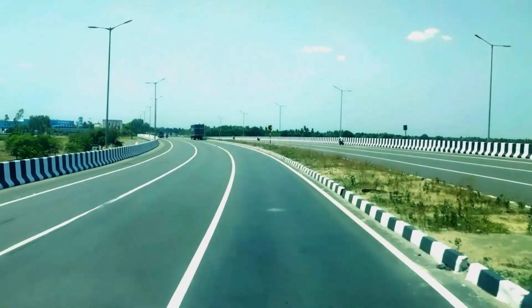Median widths vary greatly depending on available land and highway category. Some medians may be as narrow as 1.2 meters, while expressways may use very wide landscape medians. Where the median width is small, raised concrete curbs or crash barriers are introduced in narrow medians. In wider rural medians, standard raised median curbs are generally around 150 mm to 300 mm. Sometimes the open separation itself is sufficient.